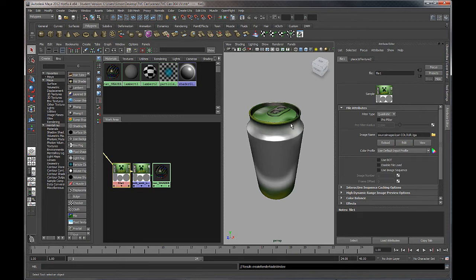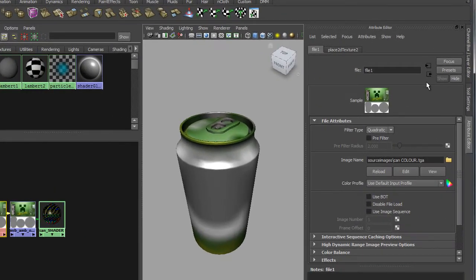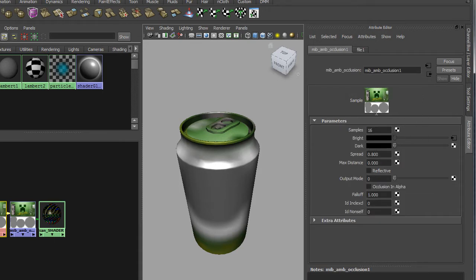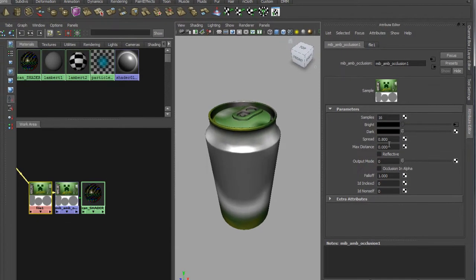All right, so I've just got to get back across to that ambient occlusion setting. So I'm just going to click on the go to output button just here, and it'll take me one level back. So this is the ambient occlusion node now. You can technically just select the ambient occlusion node down here in your work area, and that will bring the settings up. So what I want to do is maybe set the samples to about 64. Usually you want to keep this samples value to a power of 2 number, so that's going to be